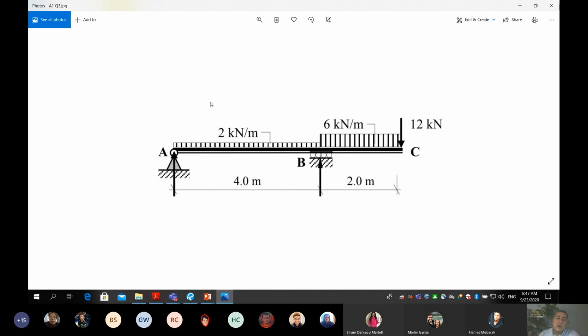You can see all the loads when we do the analysis on our beam, trying to find the bending moment, shear and axial force. We simply load our beam with a linear load. I'm not really interested to know the total weight. If I multiply 2 times 4, this number 8 is equal to the self weight of the beam between point A and point B.